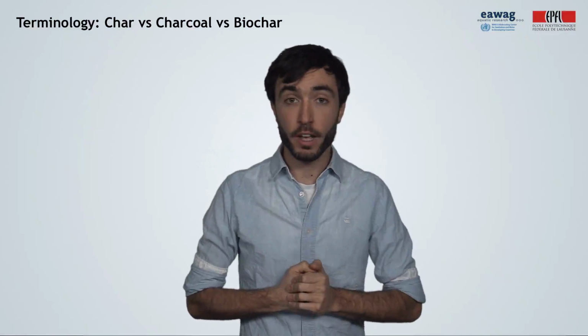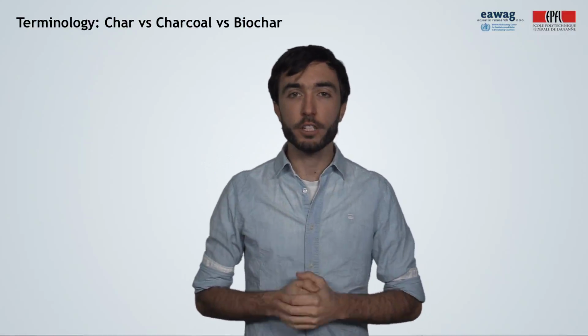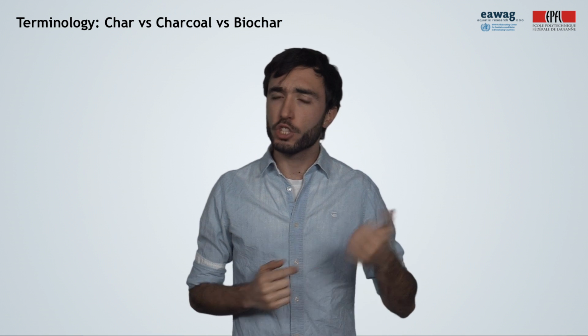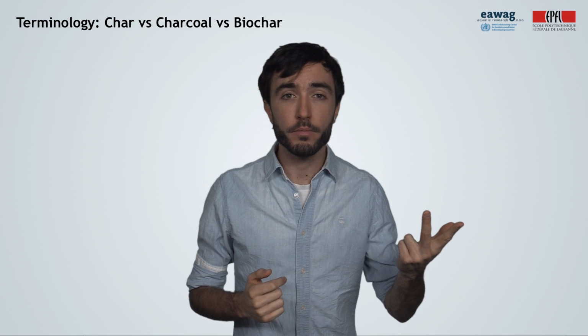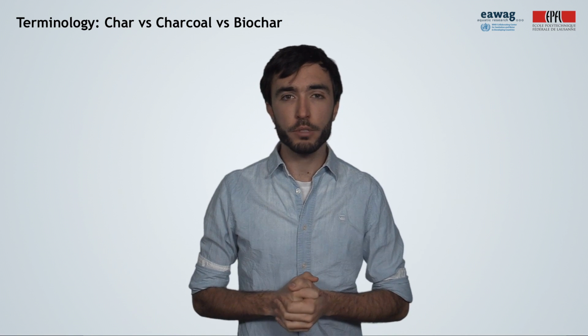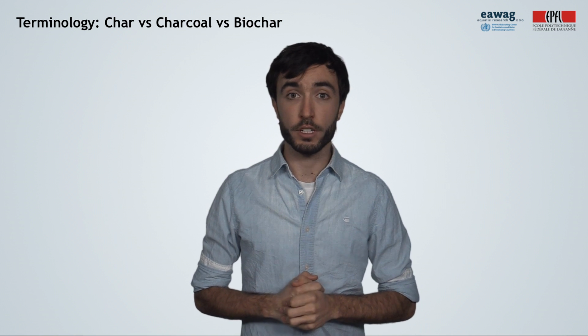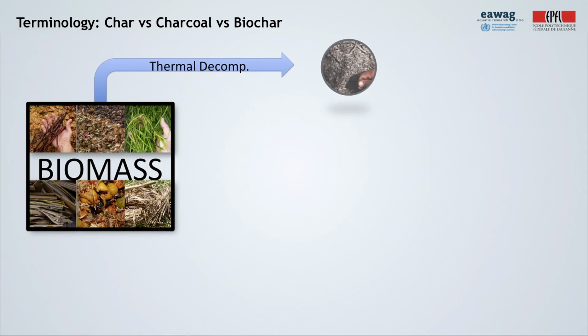Time for some clarification. We saw that char is one of the output products of these processes. But char, charcoal, biochar, did you ever hear these terms? Do you actually know what they mean? Let's see what their differences are. The term char is generally used for the solid product obtained from the thermal decomposition of any biomass, which has a high heating value of approximately 25 to 28 megajoules per kilogram.